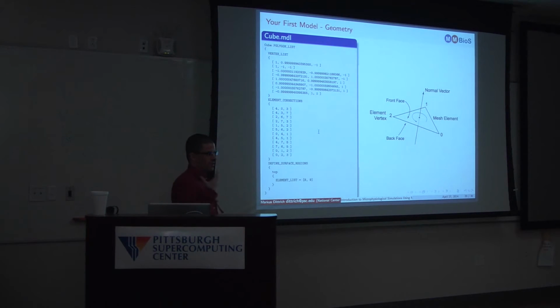So this is why I mentioned this. The consistency of the orientation is really critical to define topology. If you don't have that, there's no inside or outside. It's just a mess. It might look good, but it's computationally not a valid description of your topology. So keep that in mind. If you're just using CellBlender, that's probably of no concern. But if you have some other source of geometry, you should think about this. And in general, it's always good to check. Any questions about this?